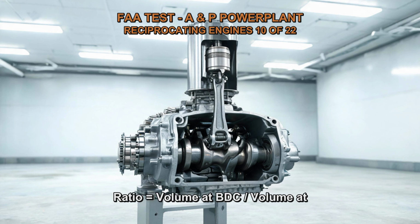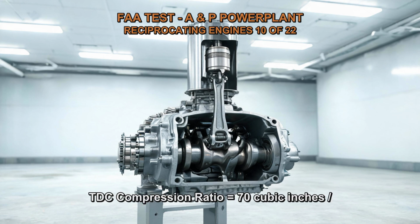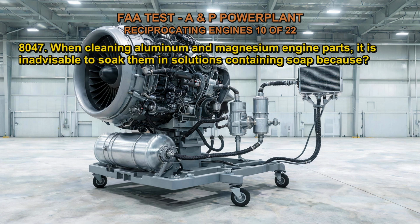Compression ratio equals volume at BDC / volume at TDC. Compression ratio equals 70 cubic inches / 10 cubic inches. Compression ratio equals 7:1.